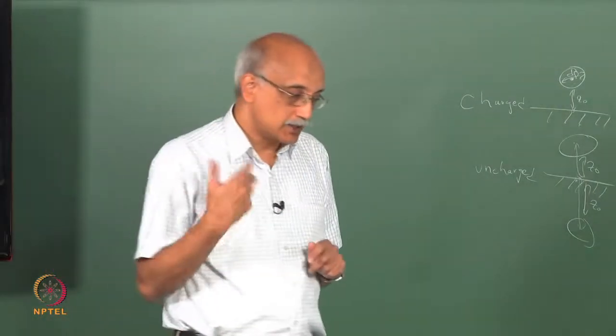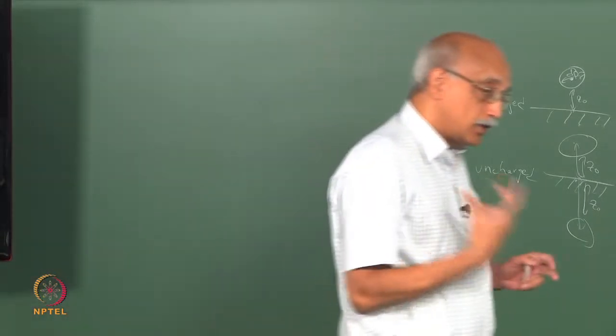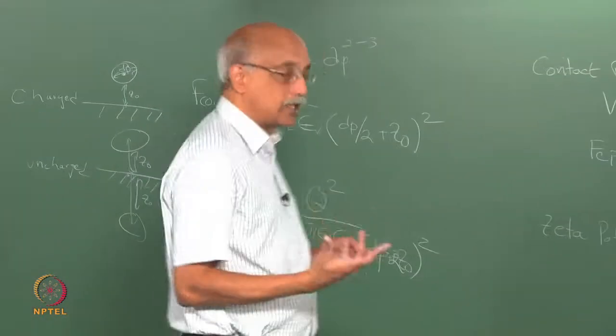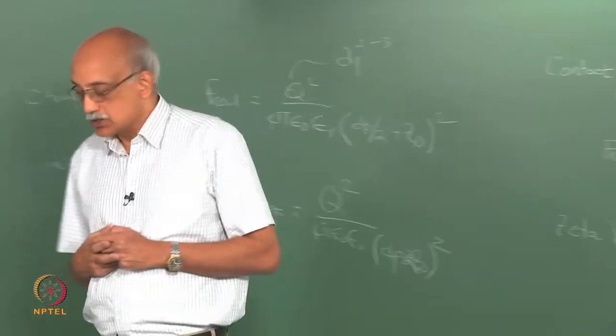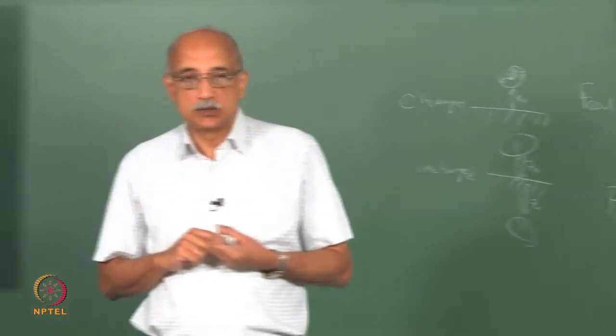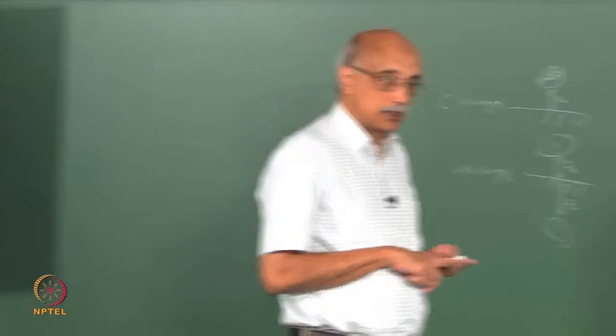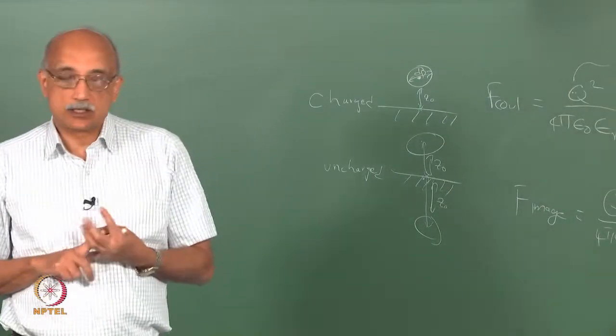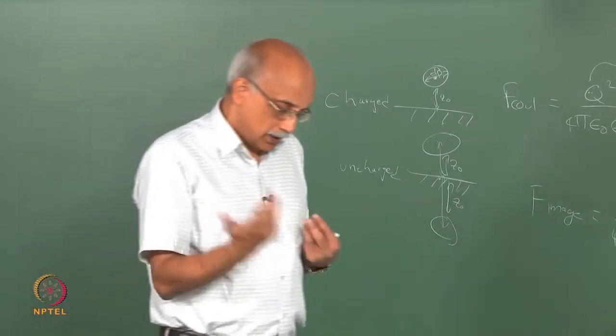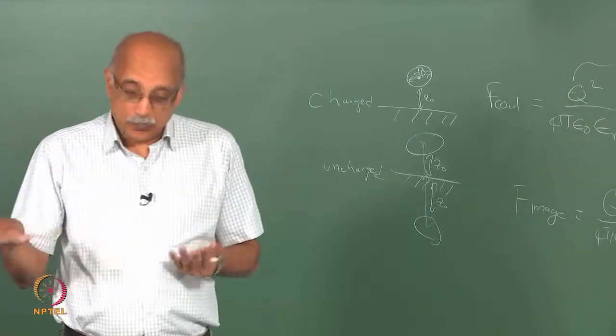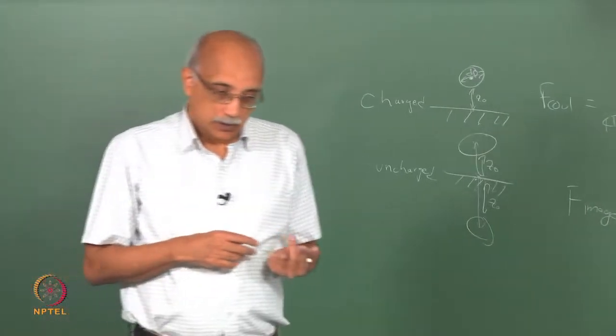So, one of the parameters that people vary and try to optimize in this chemical mechanical planarization type of systems is the pH value. Of course, the electrolyte concentration is another major variable, as is the size distribution of the slurry particles before you start the slurry process.